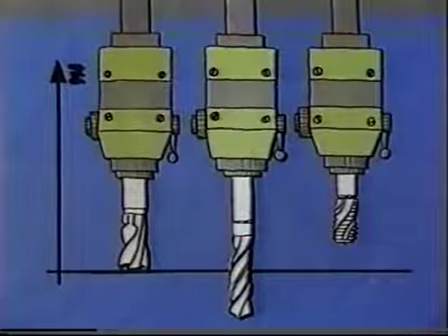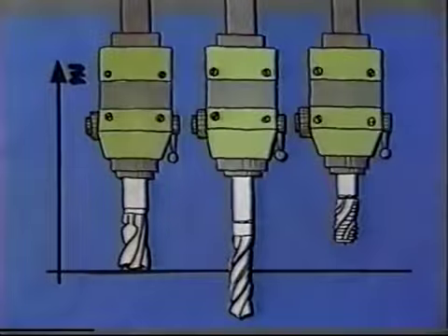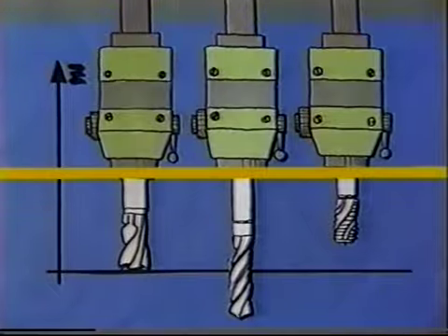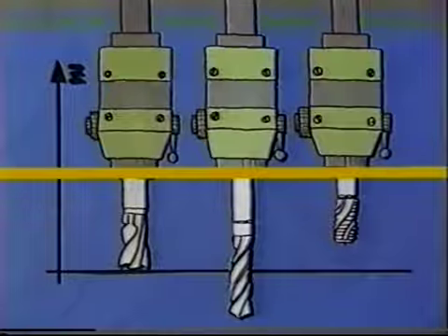Because if the workpiece 0 point, for example, is set using the finishing tool, the control system accurately notes the position of the spindle nose for Z equals 0. It always travels back to this position whenever Z equals 0 is programmed. If the roughing tool is longer, for example, the control system could possibly move the tool in rapid traverse and wind up hitting the workpiece.